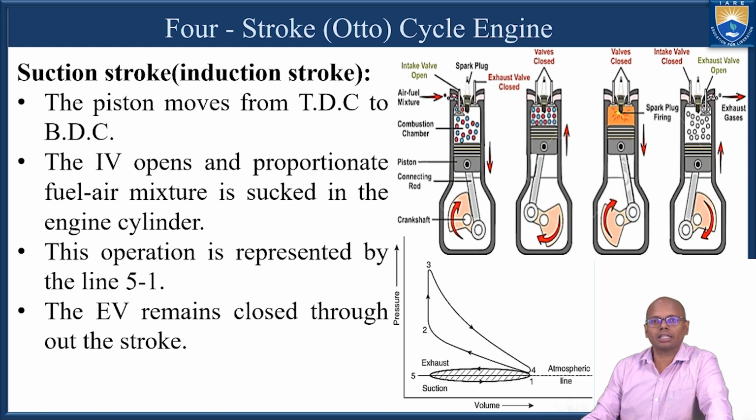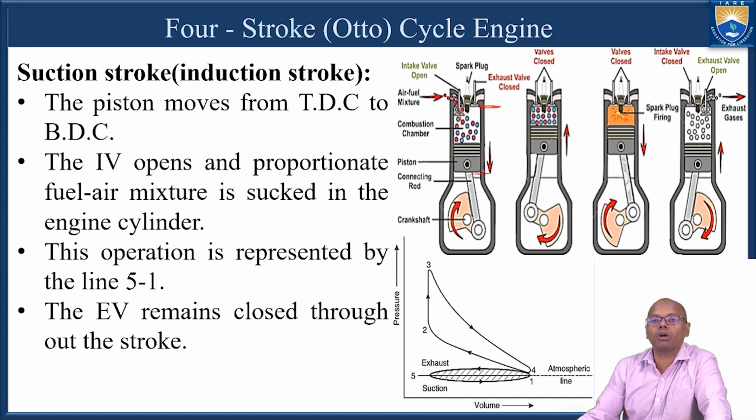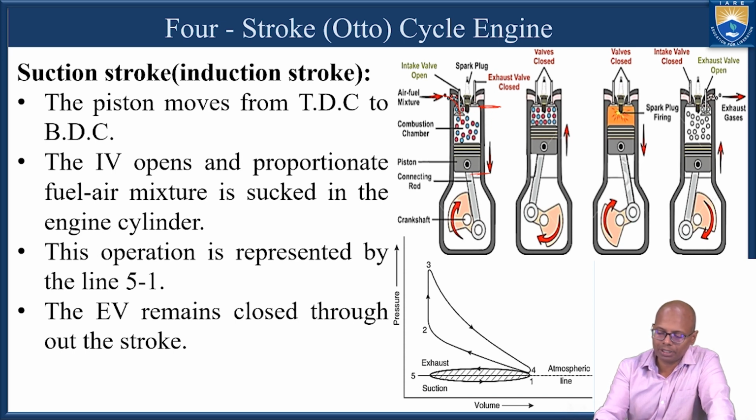Now what is this suction stroke? The suction stroke is also called the induction stroke. Why? We are inducing, we are allowing the air fuel mixture into the cylinder. Before this suction stroke starts, the piston will be at the TDC, the top dead center, and this is the BDC, the bottom dead center. So during the suction stroke, the piston moves from the TDC to BDC.